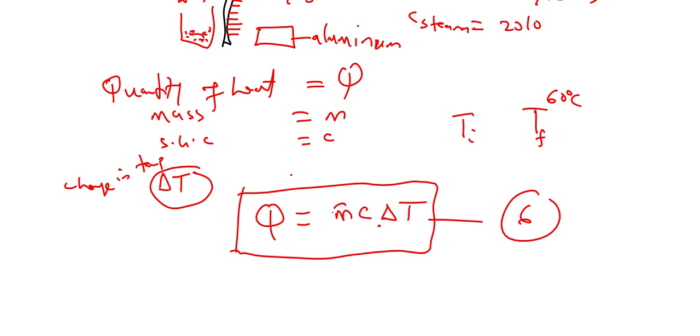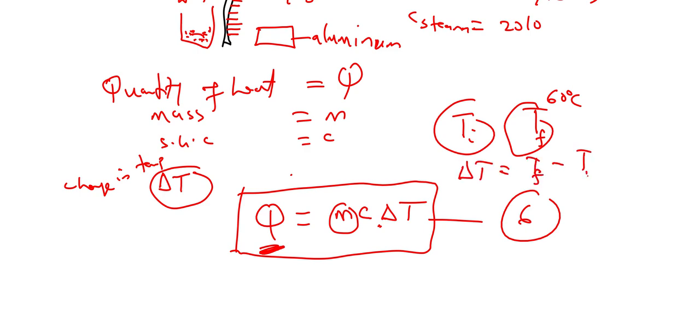So if you know the mass of the water, this is the quantity of heat that you need to supply to increase the temperature from the initial temperature to the final temperature that you want. You use the mass of the water multiplied by 4185 joules per kilogram per degree Celsius, then multiplied by the change in temperature, which is the final minus the initial. So this delta T is the final temperature that you desire minus the initial temperature of the water. So let's take a simple example.